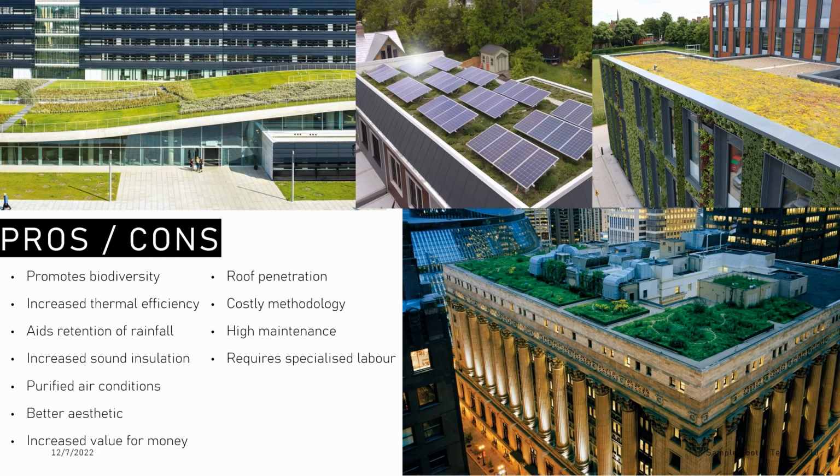The risks associated with the green roof usually result from poor construction of the system or with incorrect materials that have been used. If installed incorrectly, root penetration can occur where vegetation grows through the structure. This can result in the roof leaking or potentially collapsing. Green roofs are also viewed as an investment due to the costly methodology. They are limited to cheaper alternatives as the system requires a quality installation process using quality products.